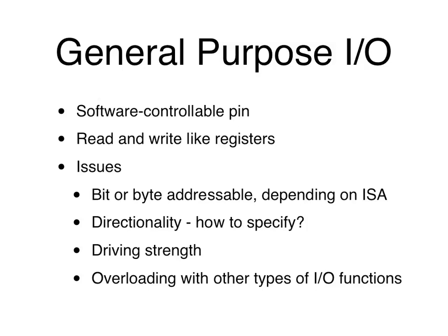But then that sometimes is not as convenient, and that conflicts with providing as many features as possible to you. So what happens very often is they reuse the same pins for different functions, but you have to choose one out of n functions at a time. And one of those happens to be general purpose I/O. But if you're not using those pins, then you can configure those pins to be some other functions. So they reuse a lot of the same pins, just because having too many pins is costly.